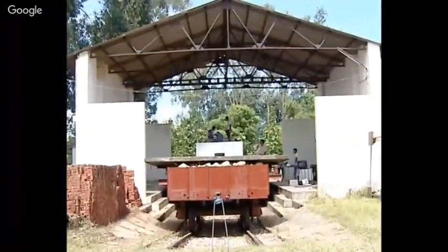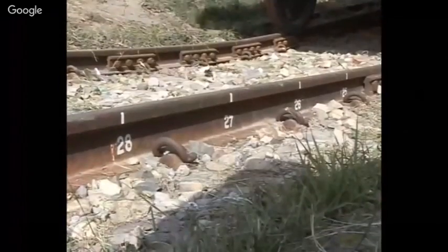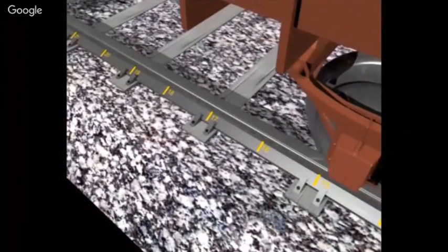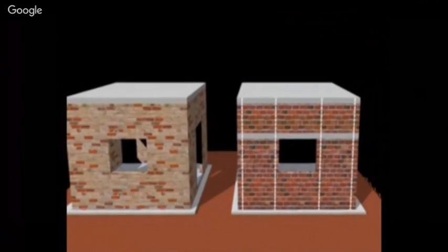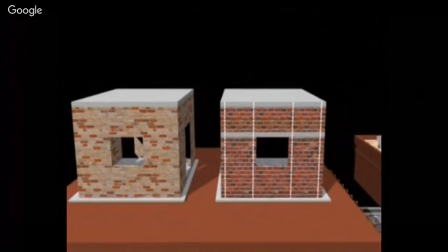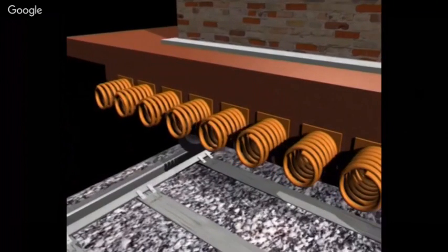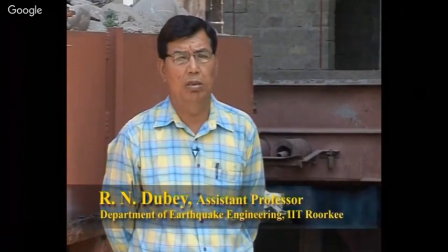Shock table provides a 36-meter long railway track having mild gradient on either side. The rails are marked at half-meter intervals as a guide for positioning the wagons before releasing to achieve the desired impact. Shock table forms a rigid steel platform which is used as a base for dynamic testing of building masonry models. 10 helical steel springs have been mounted on both ends of the table to convert the impact into a quake-like wave. Loaded wagons are placed on the track inclines on both sides of the shock table. The weight of each wagon is adjustable.